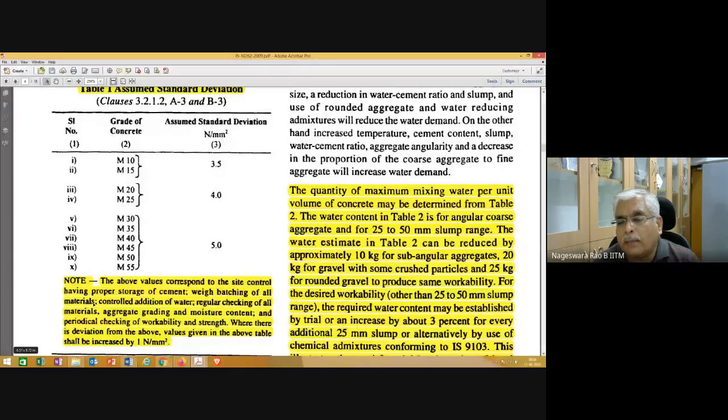When you are filling some pebbles in a jar, the quantity that goes into the jar depends on how you shake it. When you vibrate it a little after putting a few pebbles and slightly shake it, the pebbles will adjust properly, and then you can put in more pebbles. The simple experiment. So volume is going to depend on how good your packing is. That problem is not going to be there for weigh batching.